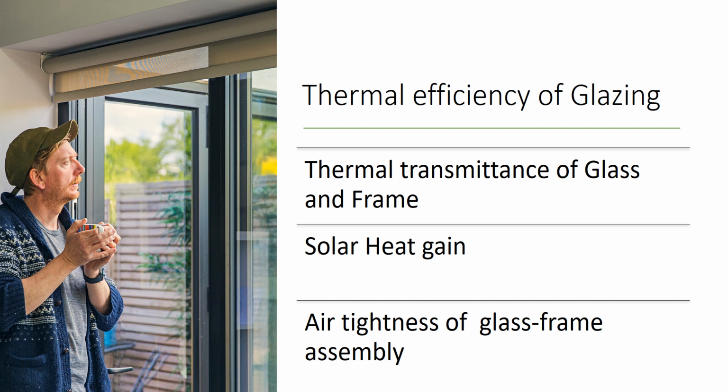Based on the climate context, the site context, and the orientation of the wall, we decide what type of opening and what type of glazing system, and whether you need solar protection or need to allow solar radiation. These things have to be decided first, and then we utilize these material assembly concepts and design shading devices accordingly based on our need.